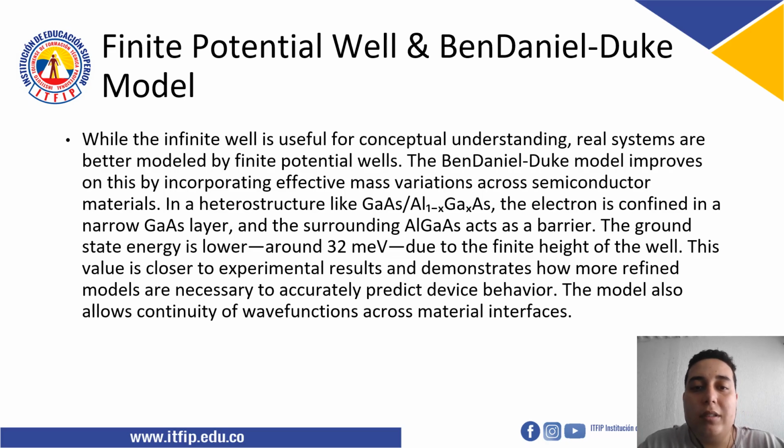Finite potential well, the Ben Daniel-Duke model. While the infinite well is useful for conceptual understanding, real systems are better modeled by finite potential wells. The Ben Daniel-Duke model improves on this by incorporating effective mass variation across semiconductor materials in heterostructures like gallium arsenide over aluminum gallium arsenide.